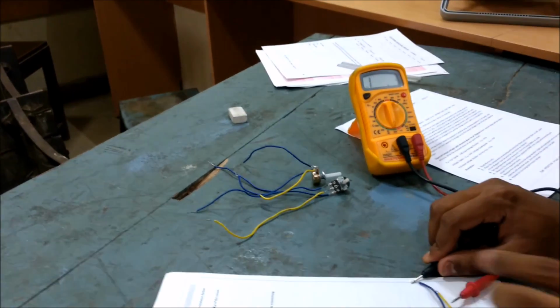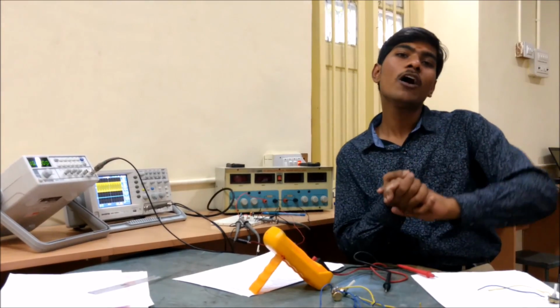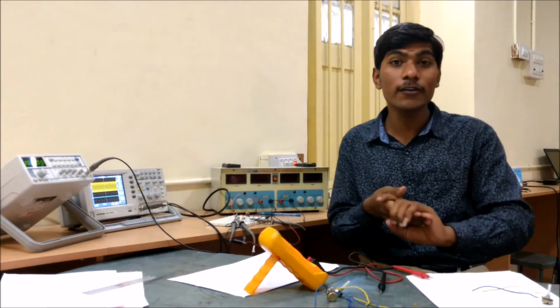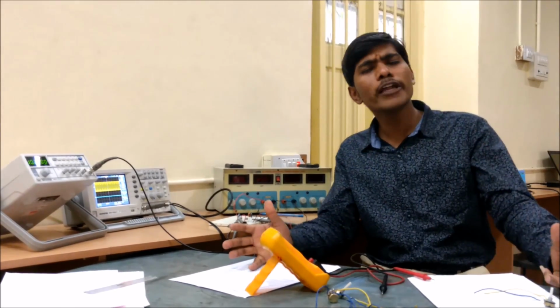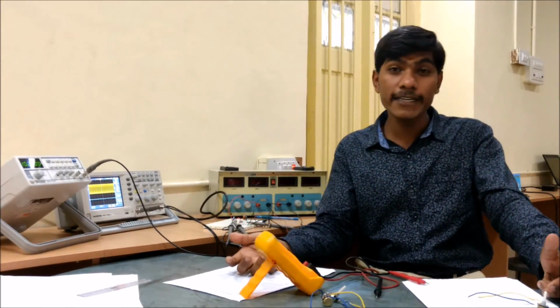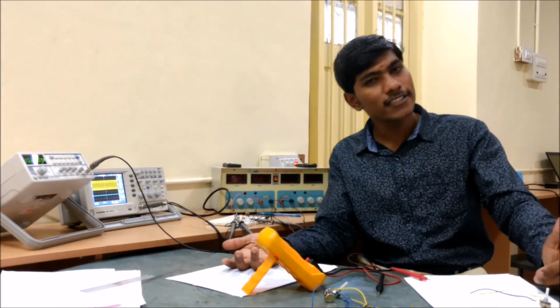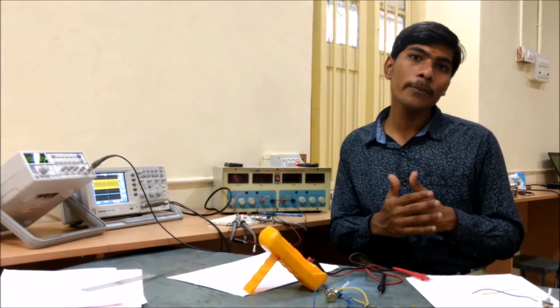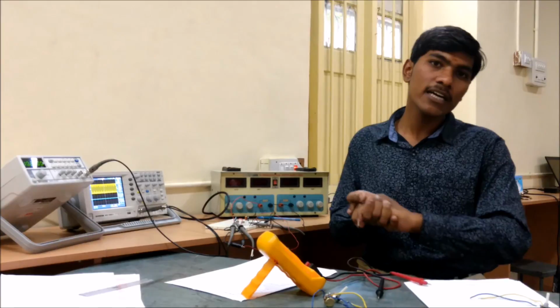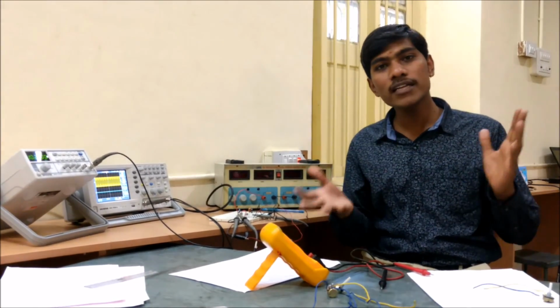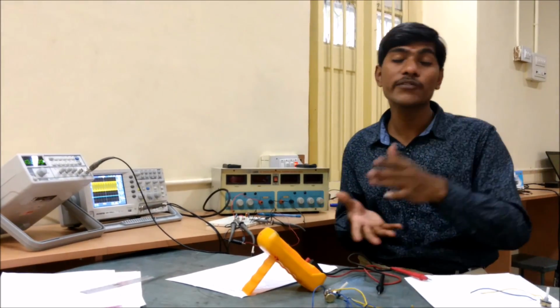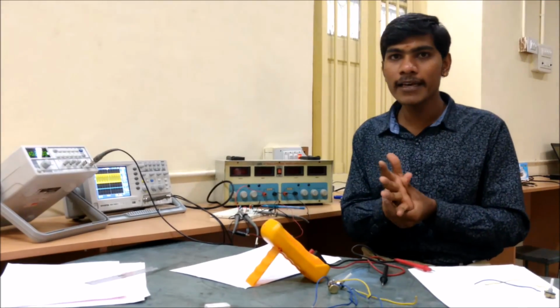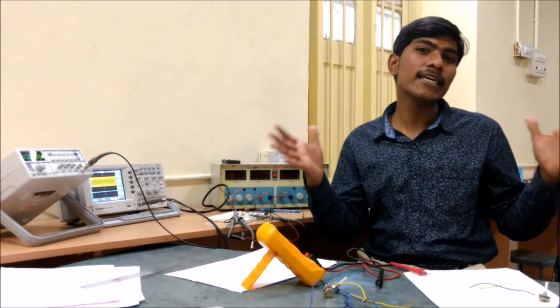It's good. Okay, guys, this is all about how the impedance varies. Without bootstrapping, the input impedance is in terms of 700 to 800 kilo ohms. With bootstrapping, it's 1.78 mega ohms. So it's a big improvement in impedance, and we can see that the output impedance is also much lower than our original impedance, that means 470 ohm. So this is all about the Darlington emitter follower experiment.